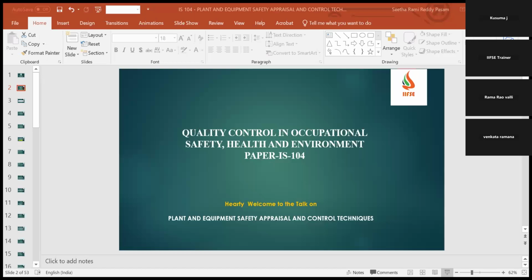Then they do a study. The study, as I mentioned, HAZOP, is one of the studies on their process, to see the deviations and also to have the safety improvements which are necessary. For the exclusive purpose of safety, there is the previous approval of the plant and building machinery layout, and safety measures provided and to be provided or required under the Factories Act or rules. So they do this study exclusively for safety, not for production. This analysis completely focuses on safety improvement.